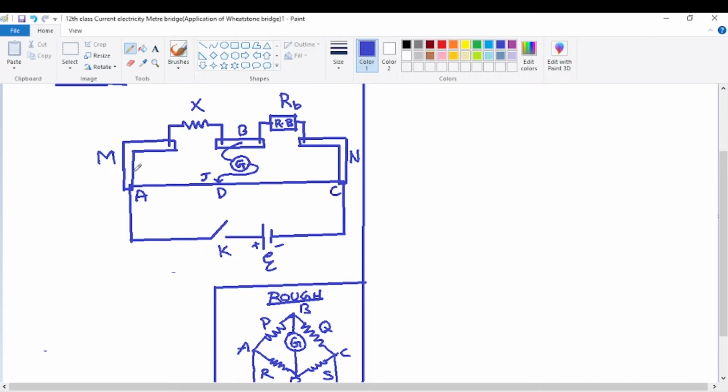It has sufficient thickness, due to which, when the area of cross section of any conductor increases, we have seen that resistance decreases. Copper or brass already have very low resistance, almost zero. Now the resistance will be almost exactly zero because of the thickness, or the larger area of cross section. That's very important here in the meter bridge construction. So the L-shaped metal strip M has almost exactly zero resistance, and the other L-shaped metal strip N also has almost exactly zero resistance.